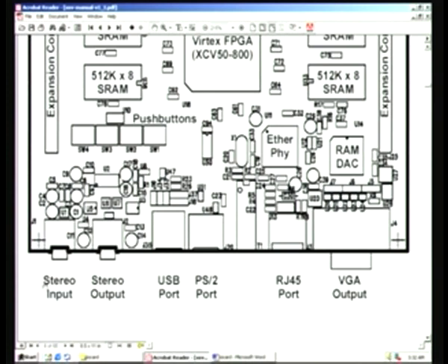and we also have a stereo input. You can give the audio input here, and for example if you want to compress the audio, you can route it here. It has a chip here which digitizes and gives a 20-bit resolution output, which can be connected to, say, the FPGA, and you can do the compression of sound. You can do MP3 for audio layer. If you want, you can do such a project using this, and for any other processing of audio signal you can use this,